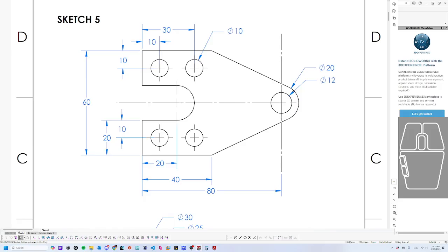I'll hit escape. I mentioned this in class, but if you draw any line or any circle or any arc and it's a solid line, i.e. it's part of the drawing, if you click on that line over here on the right, there's the options box, and you can switch it to a construction line or a center line. This is great for making references that aren't actually going to interfere with turning that sketch into a 3D object.